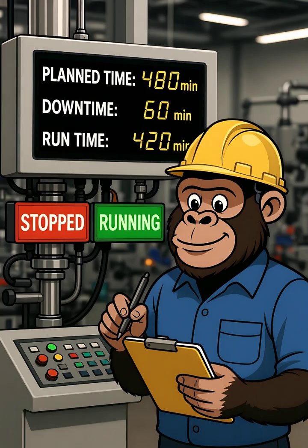But during those 480 minutes, your machine had a breakdown that took 30 minutes to fix. Then there was a changeover to a different product that took another 20 minutes. Then someone had to wait 10 minutes for raw materials to arrive. That's 60 minutes of downtime. So your actual runtime was only 420 minutes. Your availability is 420 divided by 480, which equals 87.5%.